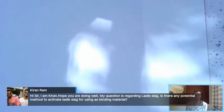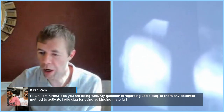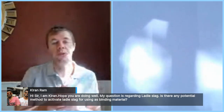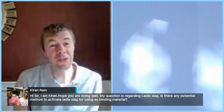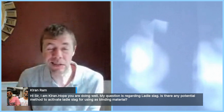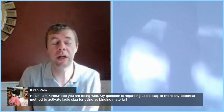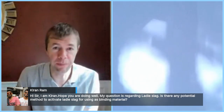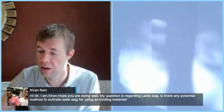The one simple way that you could study that would be to actually put it in a sodium hydroxide solution and see if it reacts, see if it does anything, and that is a quick and dirty way to see if at least Portland cement will activate a ladle slag. But hey, thanks for the question.